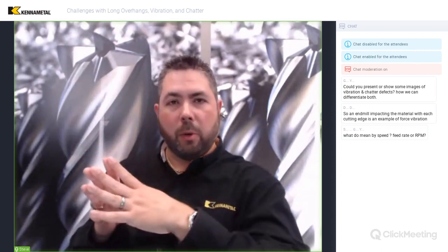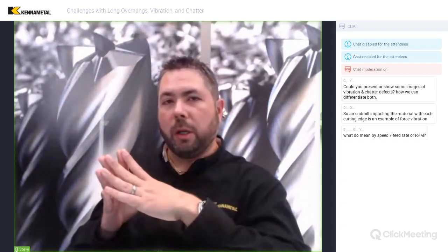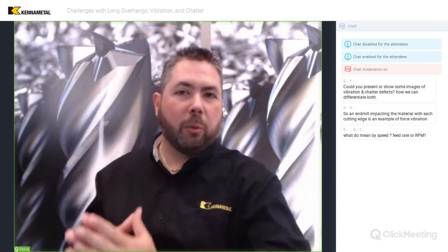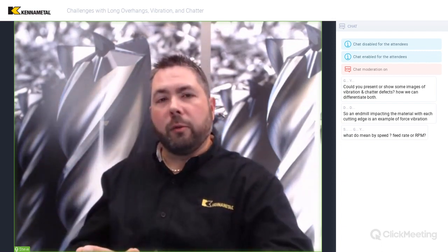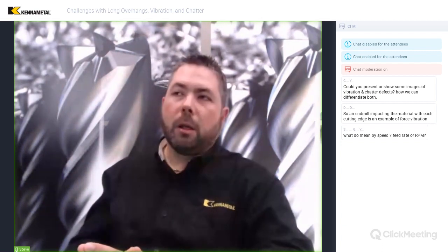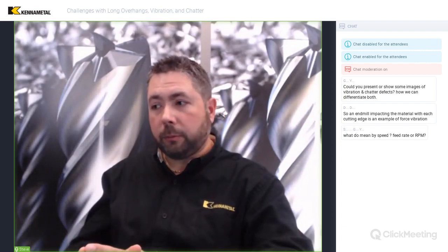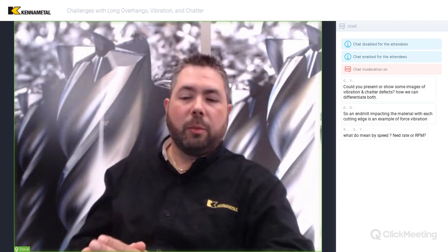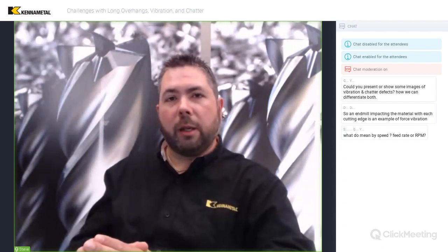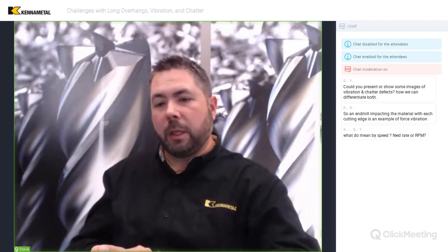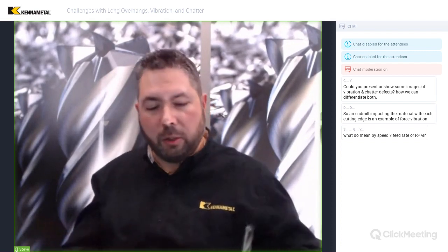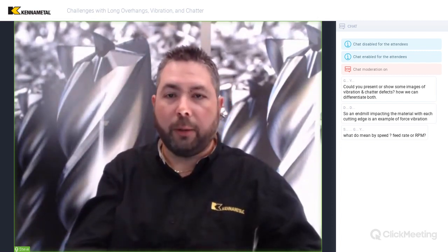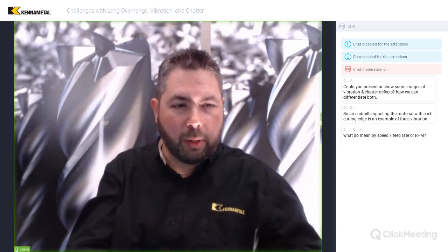When we attack the boring bar problem, it's a little different situation. You could try to follow that same approach. You could find the natural frequency, the first mode shape of the boring bar, and choose to run there. However, in order to get the easiest plug and play solution that we can give to a customer, we're approaching it a little bit differently. I've got some more stuff that we can get into with the vibration analysis, but I want to go ahead and start talking in more detail about the boring bars, how they work, and what you can do to use them. So give me a second here.